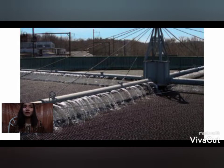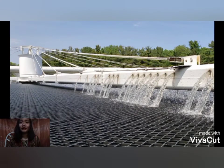So, if the slime grows in the spaces between the rocks that you built for the filters, it can fail the process or it can really fail the whole system. The volume of void spaces is limited in a rock filter. And the other problems are the odor and the filter flies.